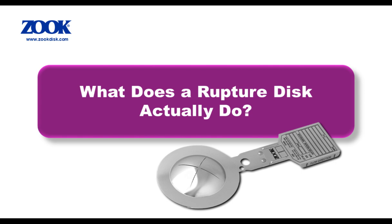Compressed gas has far more stored energy than liquid, and the burst event is much more violent. In terms of rupture disc design, a gas burst poses significantly more challenges to rupture disc engineers. A simple way to explain what a rupture disc is and what it does is to understand that a rupture disc is to a pressurized system what a fuse is to an electrical system. It's a one-time use pressure relief safety device.